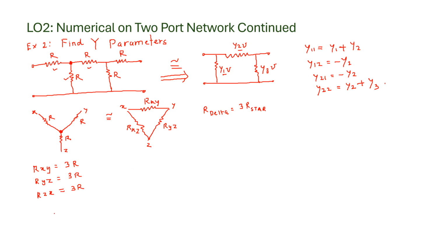So how your circuit will modify now? So your circuit will modify to this form. So you will have a delta conversion over here. So this will be there, and then you will have one more resistor over here. These values are 3R, 3R. This is also 3R, and there will be this resistor R and one more resistor R. Now this resistor and this resistor, they are in parallel, so we can combine into one resistor. So your circuit will reduce to the form 3R.